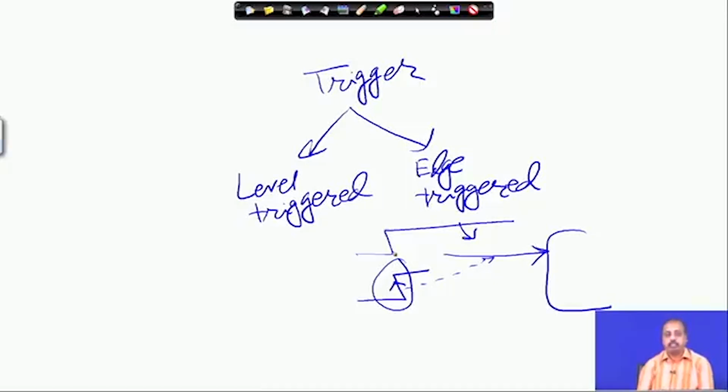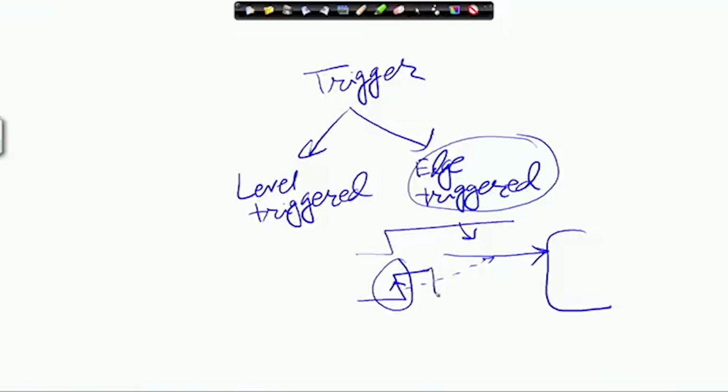Now, so far whatever we have said, 5.5 and 6.5 do not have any separate latch or memory, but 7.5 has got a latch associated with it. So, 7.5 is basically an edge triggered interrupt, because when that interrupt occurs, the latch will be set accordingly. Even if that line goes low after some time, this rising edge will be remembered by the flip flop, and this triggering will take place.